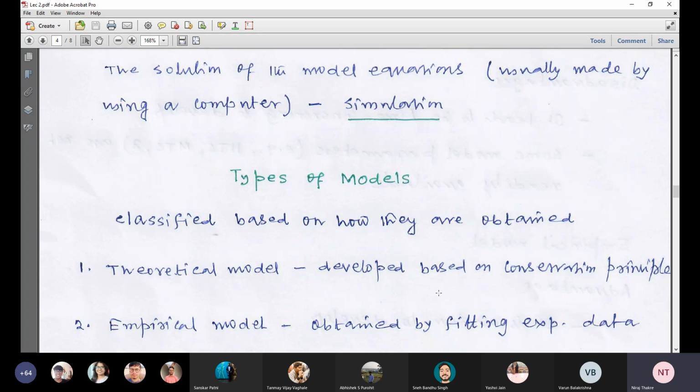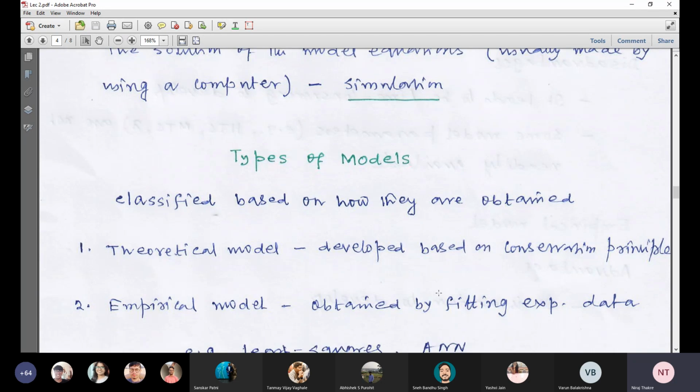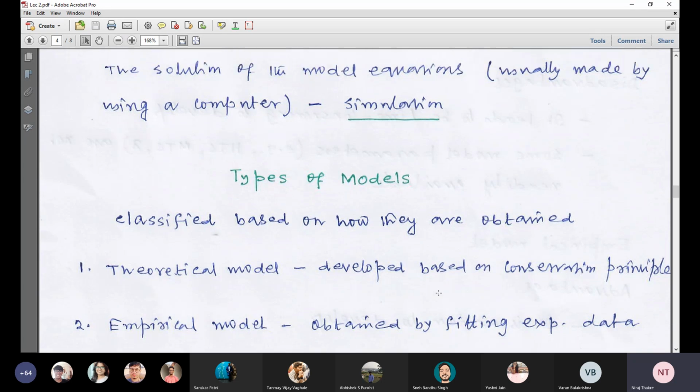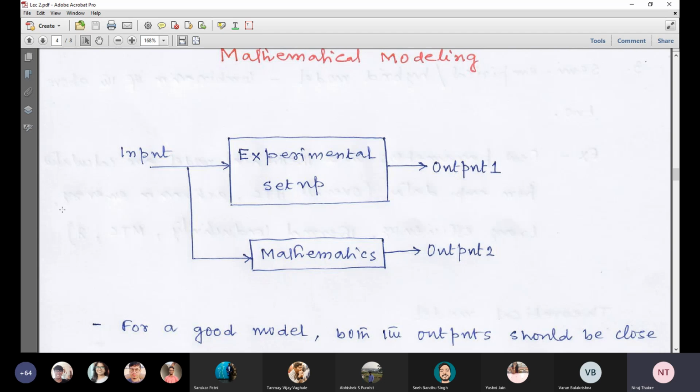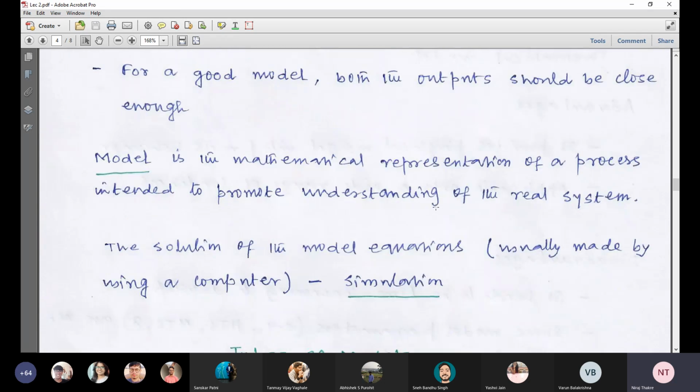If you have the input output data set, you can develop easily the empirical model. I have shown this figure, no? Here input is there, I am getting some output. So input you know definitely because you were giving, or if not, you can measure it. Output you measure and just make one table, output versus input. Then you can develop one model that is called empirical model.